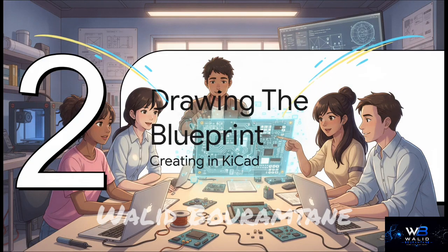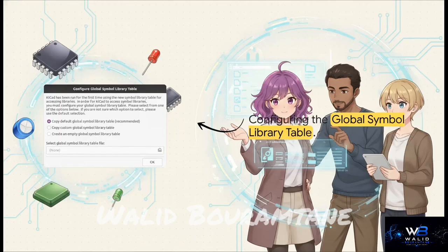Section 2. Drawing the blueprint, creating the schematic in KiCad. So how do we actually start? Well, the crucial first step is configuring your symbol library table so KiCad knows exactly where to find the parts you need. The very first time you boot up the schematic editor, you're going to get a prompt.